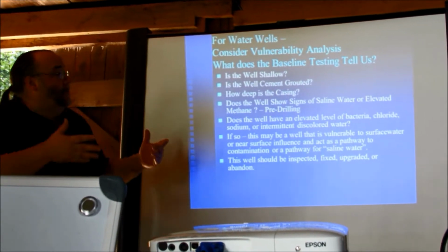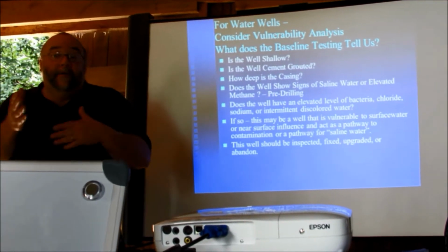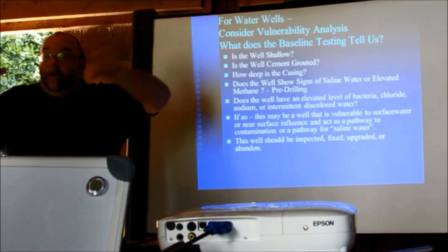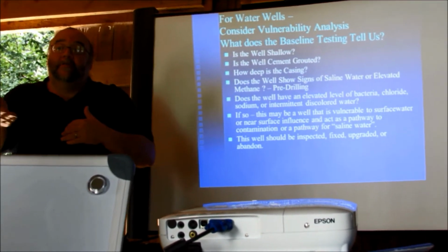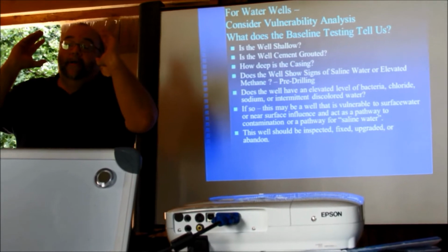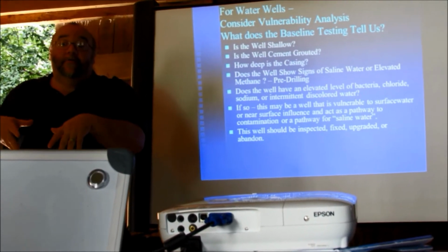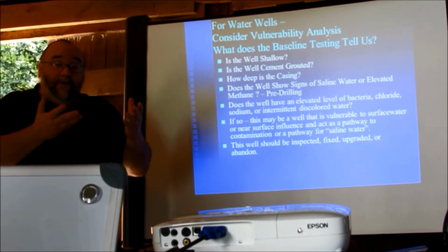And so if you're a shallow well, an older well with very little casing, a well in a pit, located maybe on the side of the slope on your way downhill, you're vulnerable typically from near surface activities. So going in and disturbing the site, drilling through the freshwater aquifer, leaks, that's when you're most vulnerable.